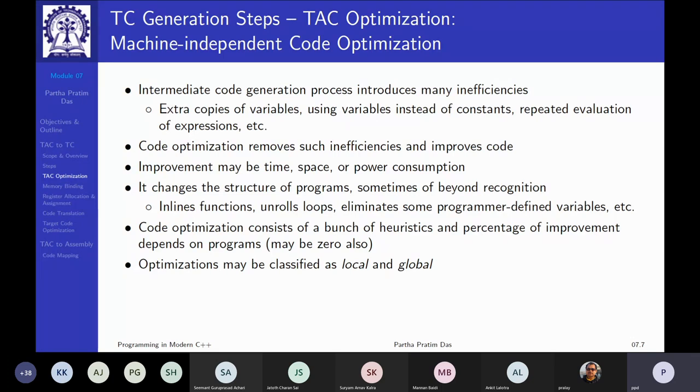So the power consumption is not only an integrated sum of the power of instructions, but also a factor of the derivative, that is, the changes that they induce, which makes the power analysis a lot more difficult. But code optimization, keeping power in mind, is also becoming very, very critical. So these are the different cost factors that will come into play here.